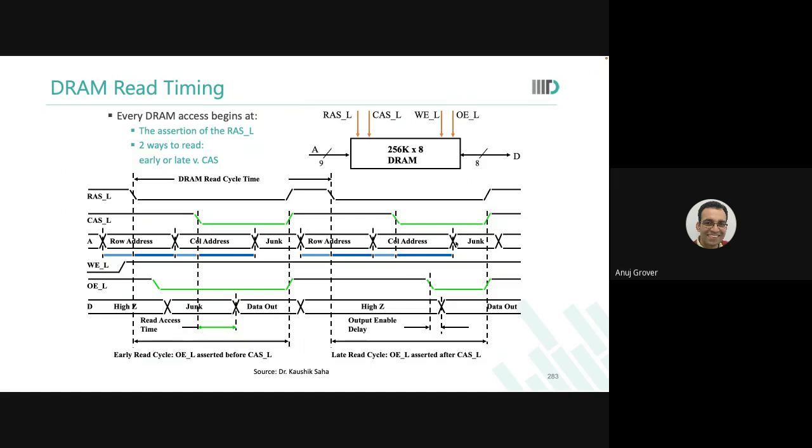So you want the DRAM write time to be non-critical, which what it means is that see, DRAM write is going to take a long time. You cannot be doing that right at the speed of the processor. Anyways, in DRAM you cannot do anything at the processor's speed. You should have much slower. So what do you do? Whatever needs to be written, you put it in a small buffer.